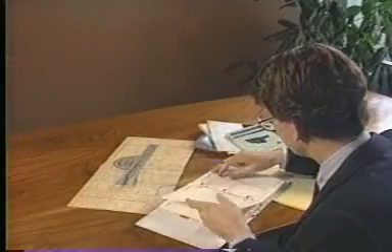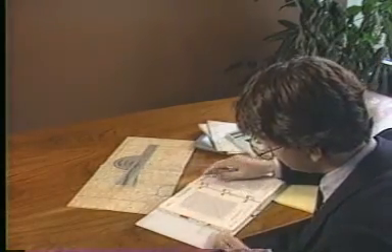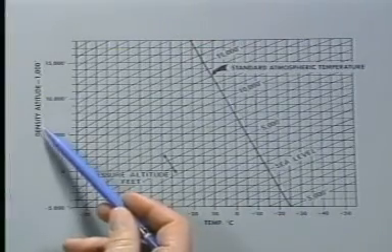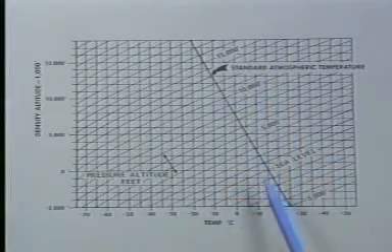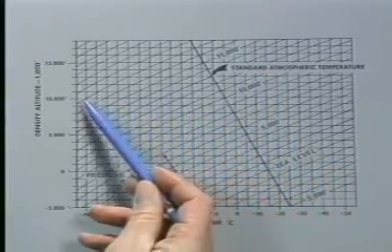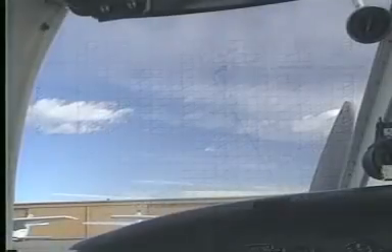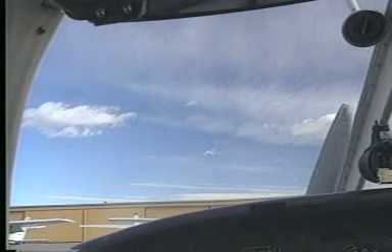One of the most effective ways to determine how your airplane will perform is by computing density altitude. Earlier, you learned that density altitude is pressure altitude corrected for non-standard temperatures, and that they equal one another only when standard conditions exist. Now let's look at an example of how density altitude is calculated and what this value actually means.